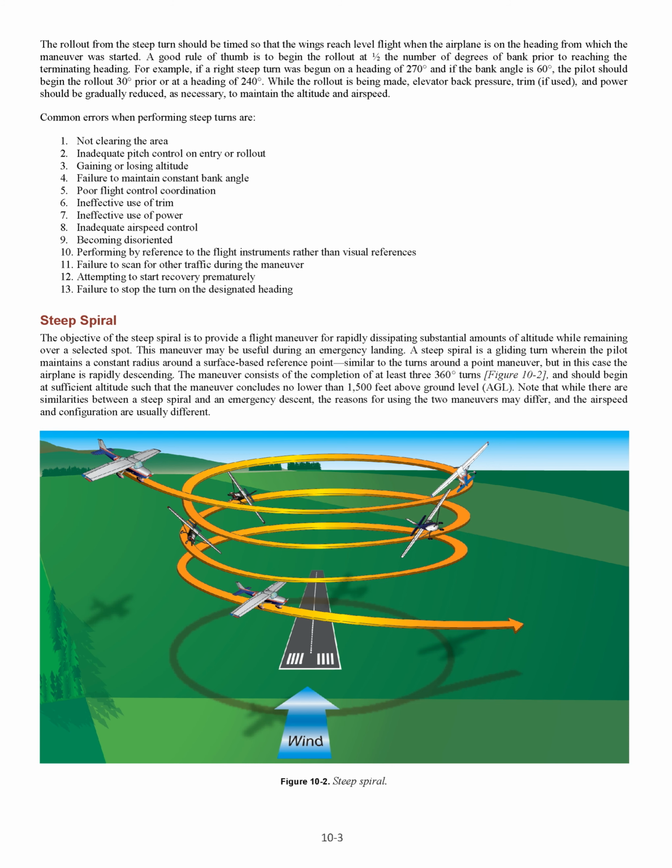Steep spiral. The objective of the steep spiral is to provide a flight maneuver for rapidly dissipating substantial amounts of altitude while remaining over a selected spot. This maneuver may be useful during an emergency landing.